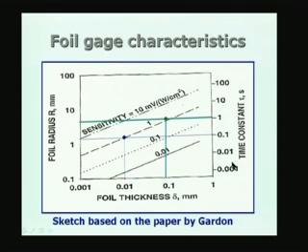If you have a very high heat flux to be measured, you require a thick foil, otherwise the foil will get damaged, it will get overheated, and possibly a larger radius for that. Okay. So, the radius delta combinations are because you may want to design different heat flux gauges for different heat flux ranges. Sensitivity is one thing, this range is the second one which one has to worry about.